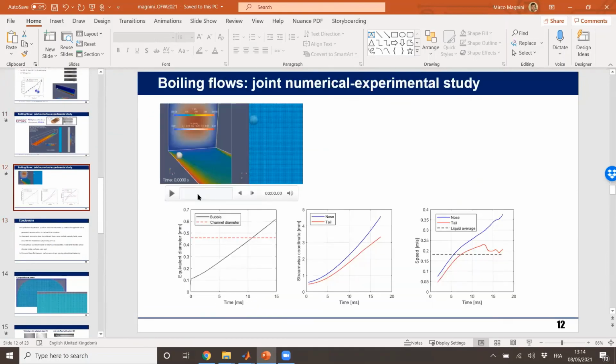Well, the problem is that just a few of the processors get many cells. Like in this case here, the bubble is still, let's say, in processor number 1, and processor number 1 gets a lot more cells all of a sudden. And that becomes the bottleneck of the entire simulation. Yes, you're refining around the interface, and the interface is moving, right? Exactly. I'm refining only around the interface, and the interface is moving. That's the problem. Okay, thank you.